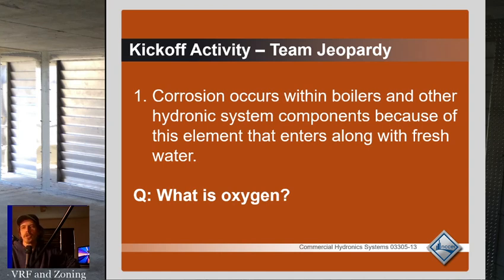You got to, on chill water especially, cut the insulation off. If you don't put the insulation back on good with a good vapor barrier, then it's going to rust from the outside in because of condensation forming on the pipe. Every time you open the system, you introduce more oxygen back into the piping system. Once you introduce oxygen into the piping system, that's going to corrode it just a little bit more until all that oxygen gets purged. And the more repairs you have to do, the more repairs that will need to be done. Because every time you open it up, you're just exposing it a little bit more to problems.